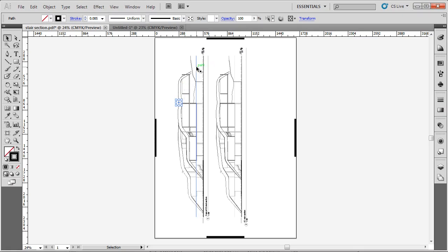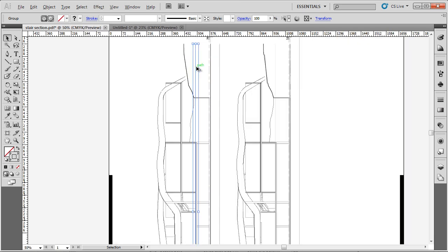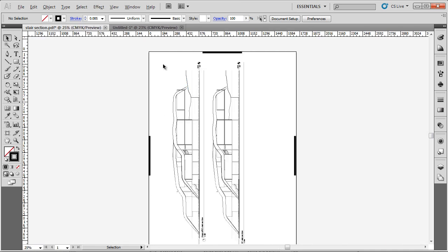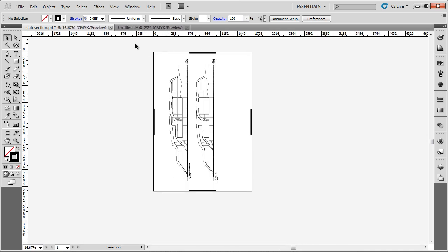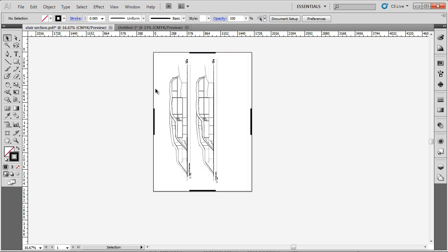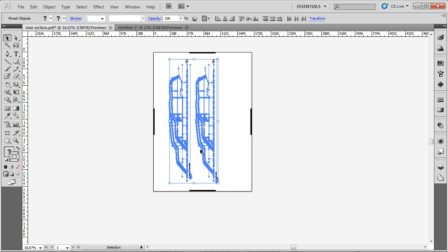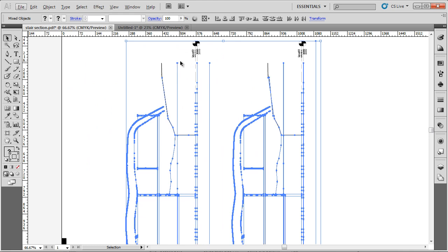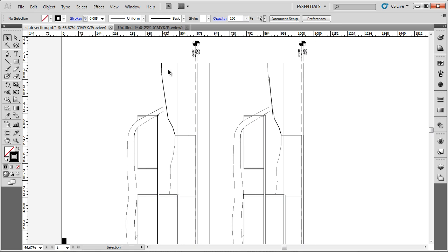So if I were to select this line here, I'll just zoom in on it by clicking on the geometry, and if I zoom out and click and drag, you can draw a marquee box which will select everything sitting inside that box. Now if I only select a proportion of the geometries, you'll notice even that this line wasn't entirely inside that marquee box, it was still selected. Anything that touches the marquee box will be selected.